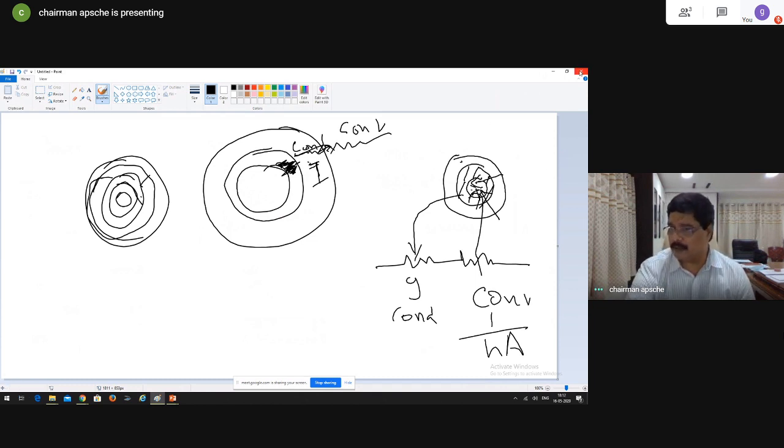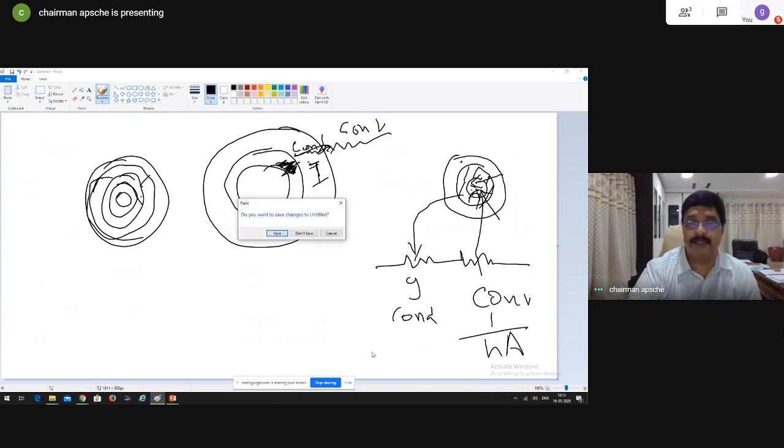Am I clear with this? So the two cases. That's an intelligent question. That's a good question asked by a student. Now, what happens when you add insulation outside? When you add insulation inside, the heat transfer continuously reduces because of the addition of insulation, because both the resistances increase. When you add it outside, conduction resistance increases and convection resistance decreases by virtue of the increased surface area. So, therefore, the critical radius applies only when you add insulation outside. Okay.